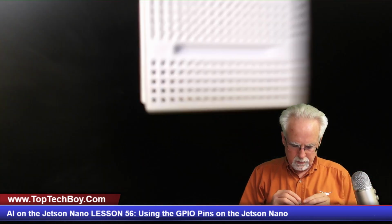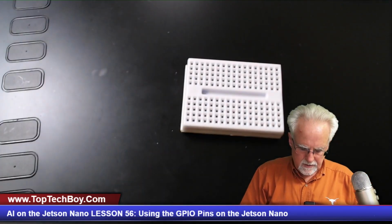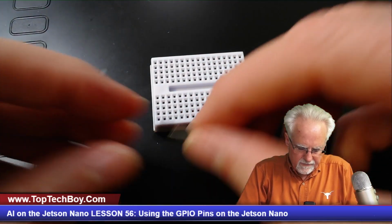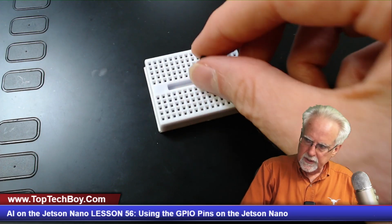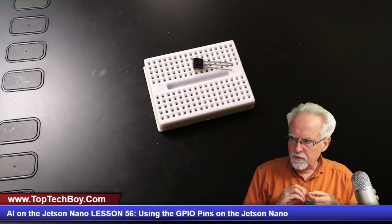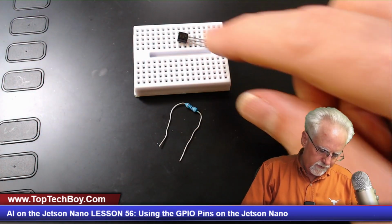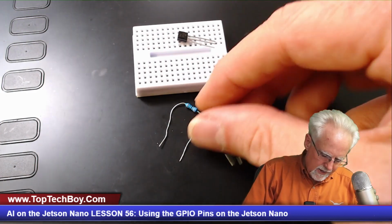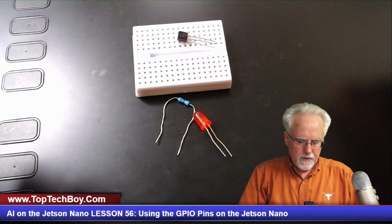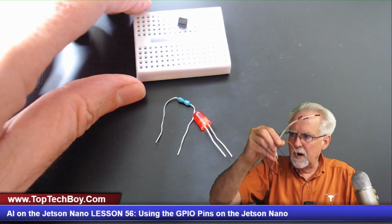So I've got the breadboard. Okay, I've got the breadboard. I've got the PN2222 transistor. I've got a 330 ohm current limiting resistor for the diode, and then I have the red LED. So let's see if we can put this up, and then of course I've got wires to hook up to the Jetson Nano.